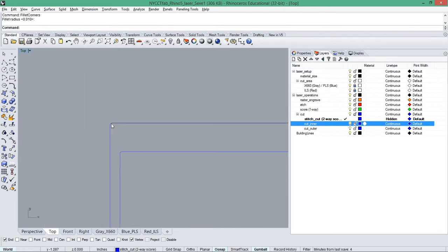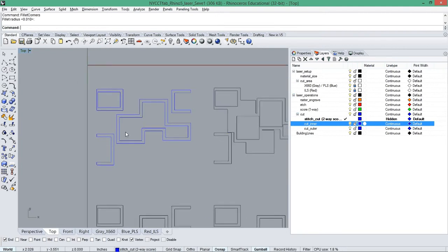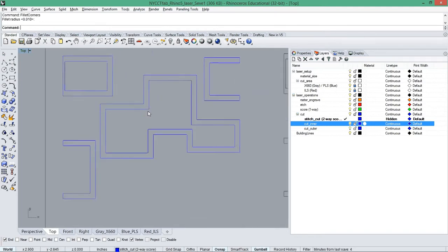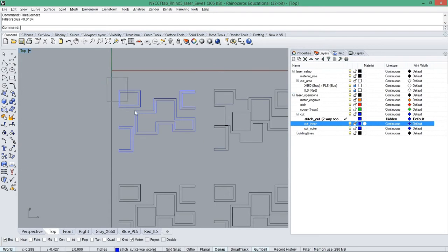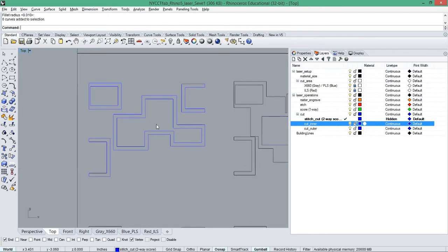If it was a straight, perfect angle, it comes, kind of stops and continues. That point is going to be less attractive to the eye, less clean in that point. So that's a recommendable thing. Again, select everything, fillet corners, okay?